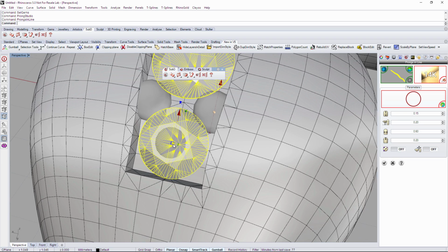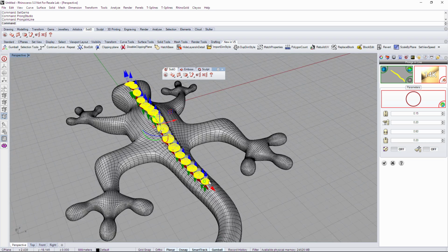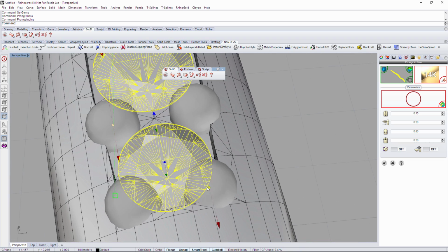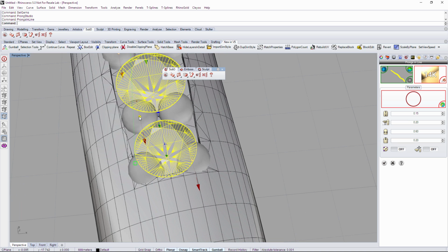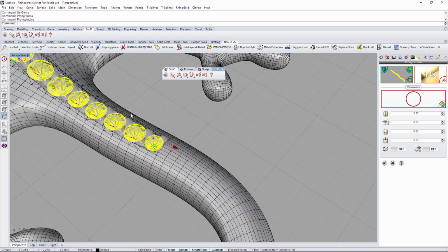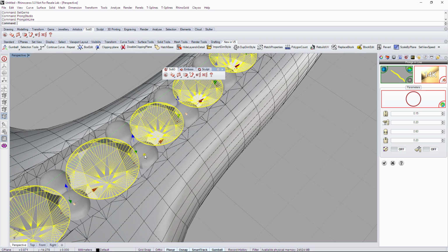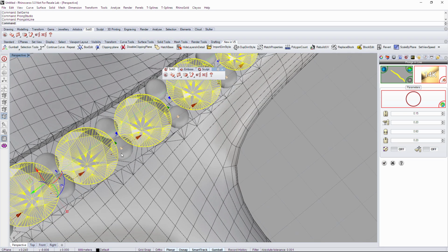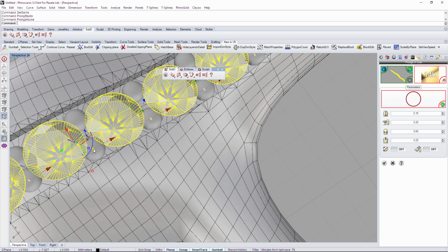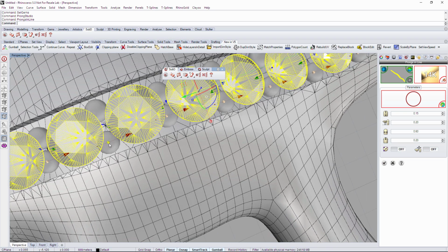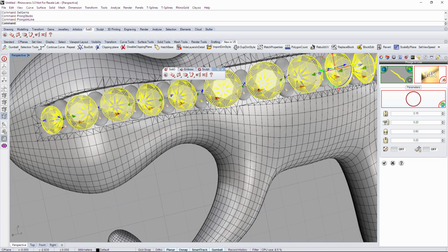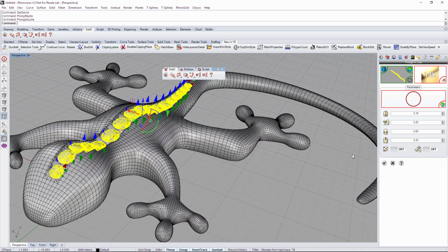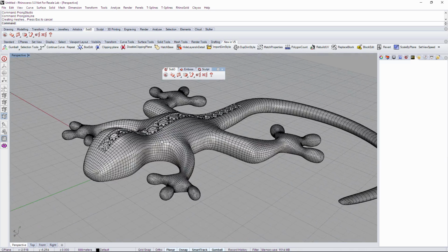So now I'm gonna just refine my corner prong, so something like that, and maybe the last ones in here, so something like that. I'm gonna make sure that those ones are just inside the channel. Okay, so as those ones are bigger gems, maybe I have to refine a little bit manually those ones in here a little bit. Okay, something like that. Okay, so there we go, we have all the prongs applied. So I just have to validate the prongs. Okay, and there we go.